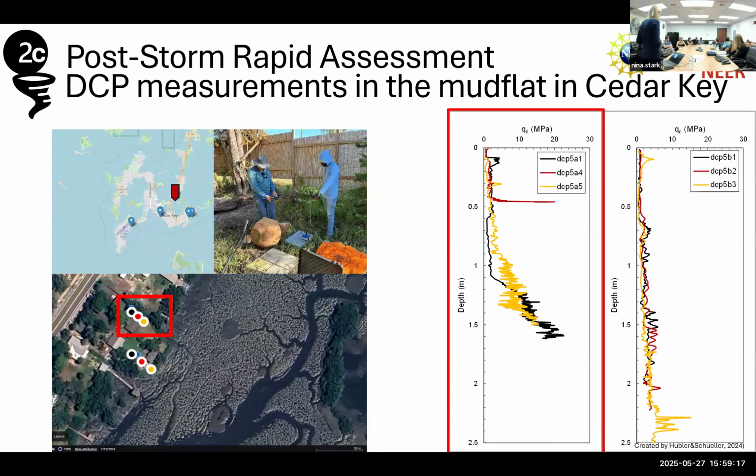It seems like it would be great value added. Not in place of some of the penetration tests, but like Peter's saying, bring all the evidence you have to bear. GPR would be great because then you get a sense of how it's structured. And if you have an analog somewhere else where you can say, okay, this is giving that acoustic impedance contrast, it allows you to get out to the tidal flats without actually training on it. Get out there so you don't disturb it. It's safe, not endangering anybody. That is good.